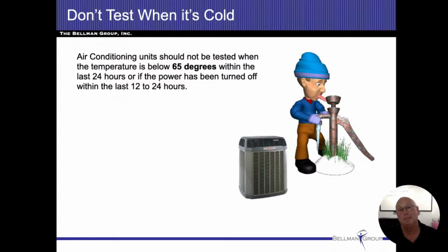But for us, being cautious, we're going to use the temperature of 65 degrees, and we kind of stick to that if it's been that temperature within the last 24 hours. All right. Now, the reasoning why we don't want to test air conditioners at a lower temperature, I need you to go back to your memories a little bit when I showed that compressor out there earlier. An air compressor can only compress air. All right. If I try to push liquid through that air compressor, then all I'm going to do is damage that air